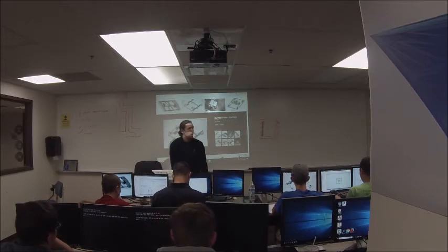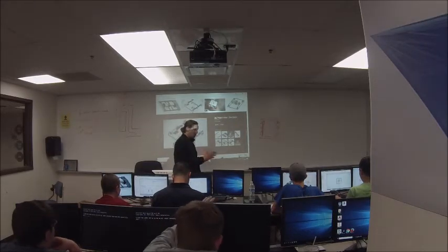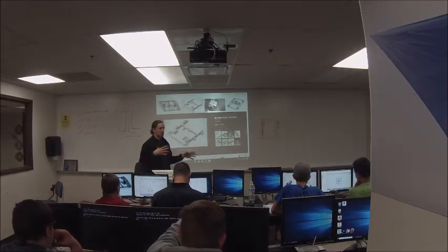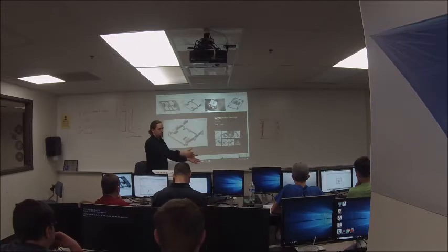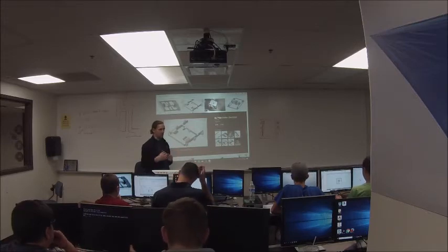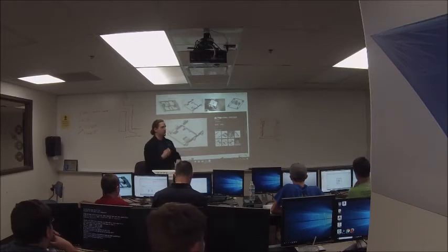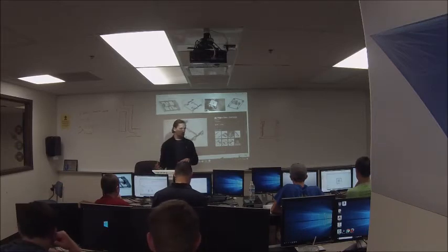They do have a lot of extra motors because you have to have a whole set of motors devoted to driving your robot sideways, whereas with Mecanum, the motors that are driving your robot sideways are the same ones that are driving it forwards, right? So the motors are serving multiple purposes on a Mecanum drivetrain, whereas on slide drive, you have to have more motors that are each serving fewer purposes, which adds a lot of weight and complexity.